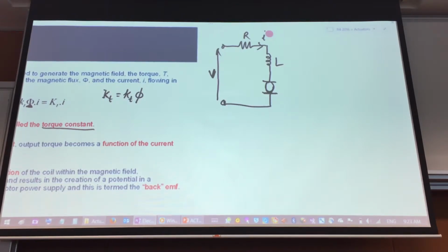If you have heard about back EMF before in earlier applications, that came about just so because your motor, as it turns, is also behaving like a generator, and is providing that back EMF. So that amount of back EMF is represented by this. Back EMF, its units is in volts.